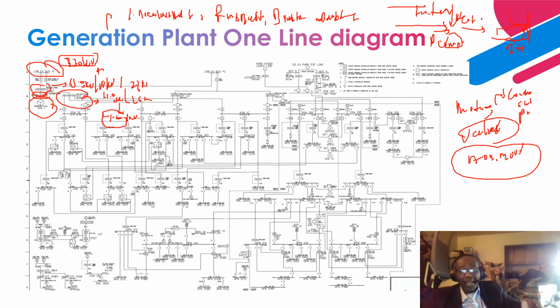That is going to provide power to motors that are rated at 4.16 kV. Then from there, you have a 4.16 kV, right? Bus schemes, right? So the next goal is to be able to step the voltage down from 4.16 kV to, let's say, 480 volts, right?